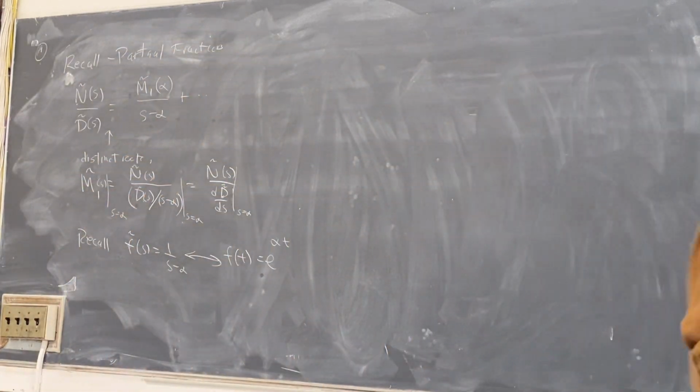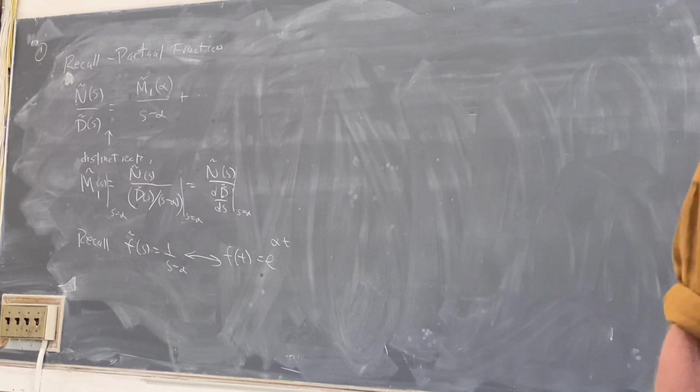And notice there is a contribution from the input when I have a step change, because that gives me an s in the numerator. The numerator is less important. It contributes to the coefficients, which are the detailed time dependence of the solution, but it doesn't contribute to the stability. The stability all comes from the denominator.